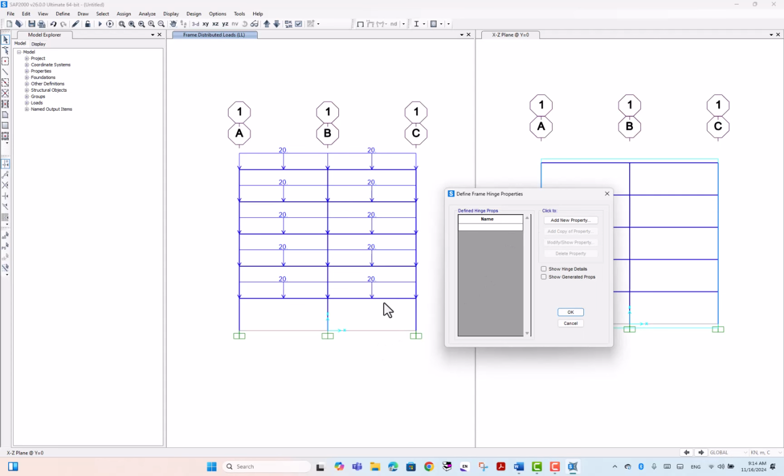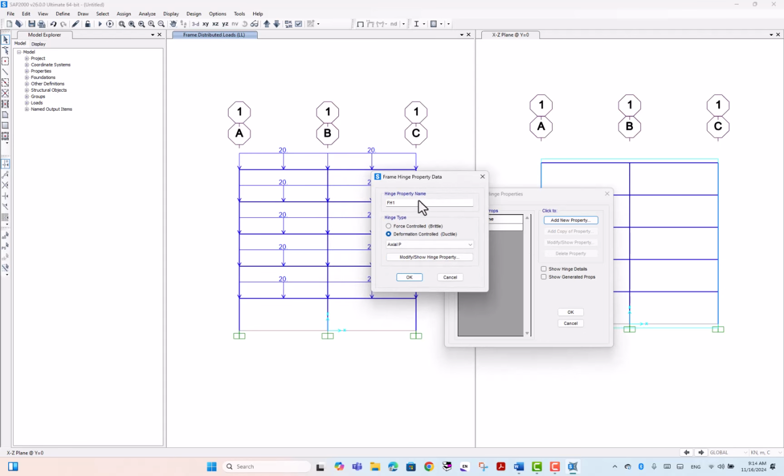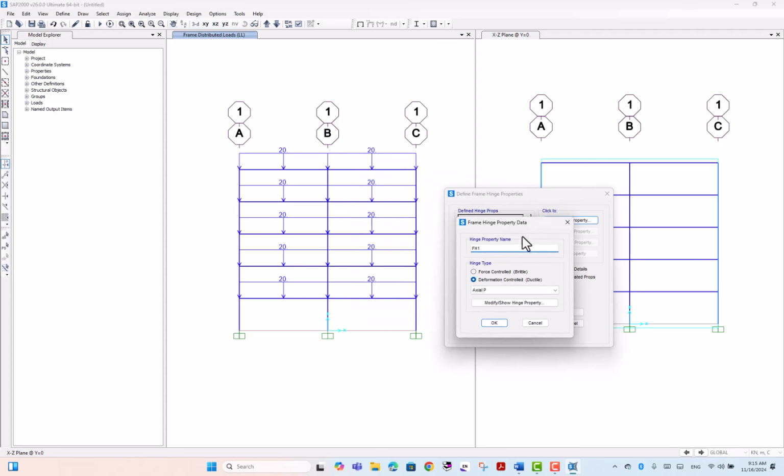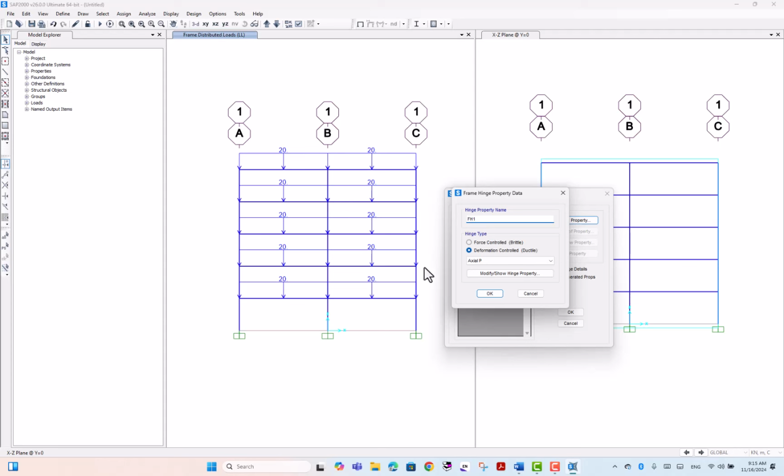A fiber model is a little bit computationally time consuming, but the hinge technique is much easier. So we do the hinge technique. So it's concrete, and here you can see it is called frame hinge, and which type of behavior you want the hinge to consider. Mostly this hinge will be damaged because of significant moments, not actual force.